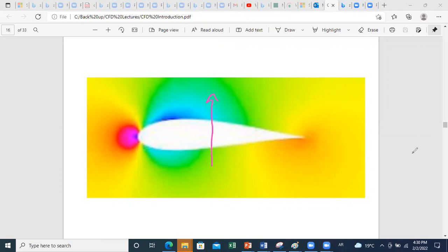Maybe for other applications it has a different purpose, so always you should set your objective and based on this you decide on the geometry. That's why we have several airfoil geometries depending on where we want to use them. In some applications lift might not matter to you, so you can make it symmetrical, and then you work on the drag effect. So it depends on your purpose from using this geometry, you decide how it should be.